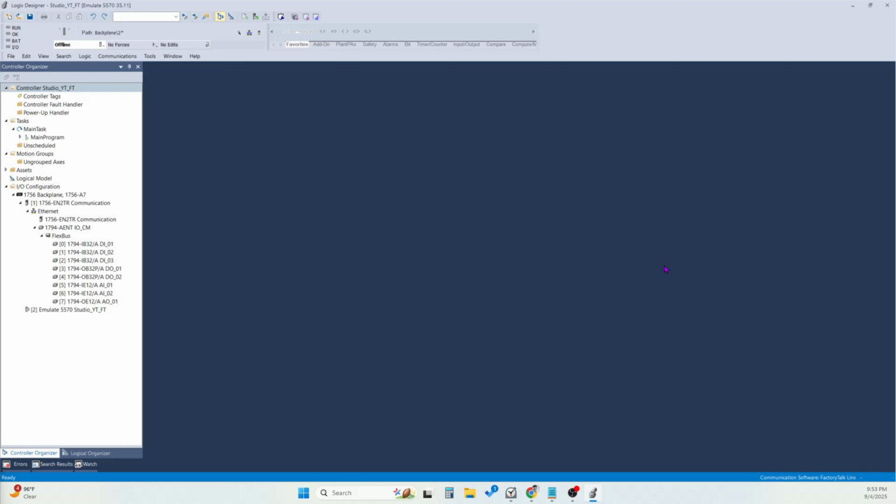Maintain push button in FactoryTalk View Studio and how to link a tag of Studio 5000 to the button. Then with the button, how you can use animation on any object, either rectangle, circle, line, button, or any other object. So, do you want to build a push button in FactoryTalk View Studio that acts like a real on-off switch? If you don't know about the momentary push button and toggle button, you can watch my old video.